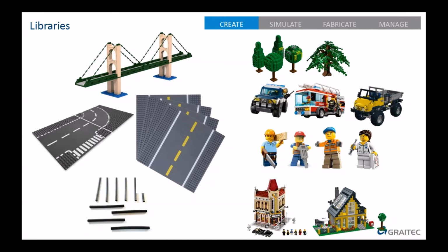Pipes and structures. There's a package installed with Civil 3D and with Infraworks, and that's called the Infrastructure Parts Modeler. That will allow you to create your own structures and model them. You can model these in Inventor, put them into the Infrastructure Part Editor, and it creates a bit like assemblies. There are 3 elements that you have, a top, a middle, and a bottom. And that will build your own parts library for your pipes and structures.